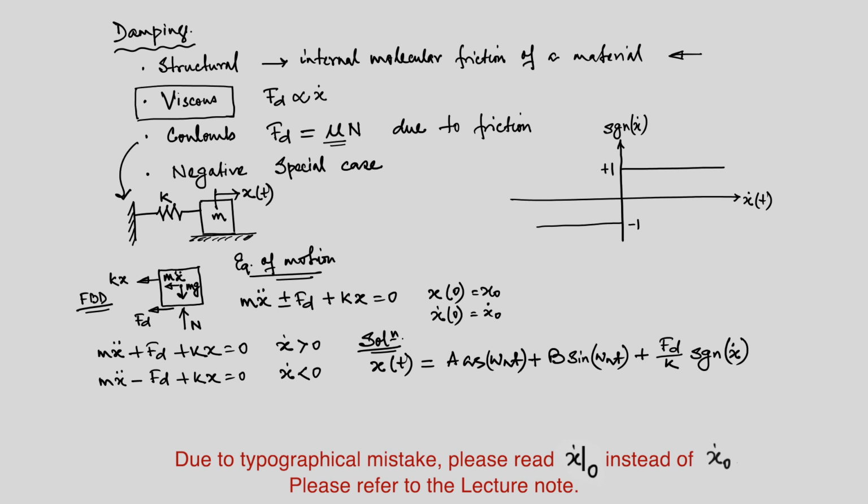Okay. So, in this case, say we assume at t equal to 0, x naught is the initial displacement and the velocity is 0. So, let us set this as the initial condition, and then for that you can easily now solve this expression to find out a and b. These are the two constants we have in this trial solution, and you can easily do this at your end just to satisfy these initial conditions. So, I leave it as an exercise.